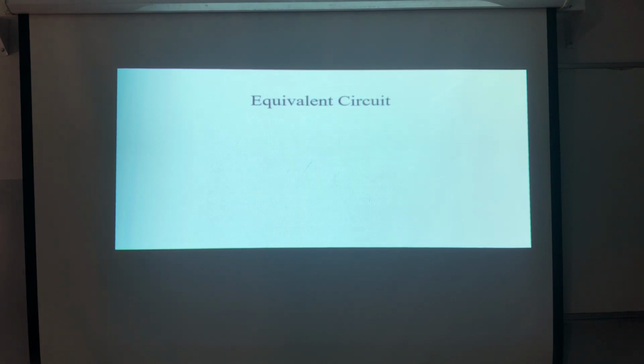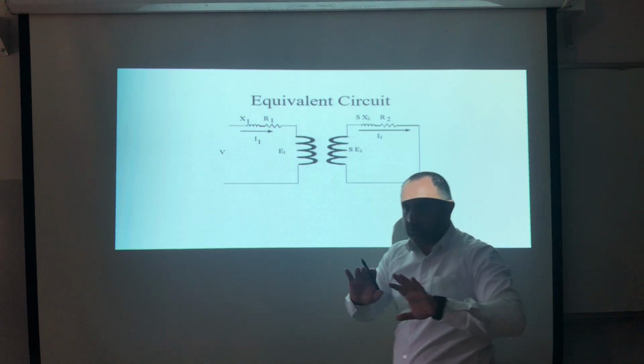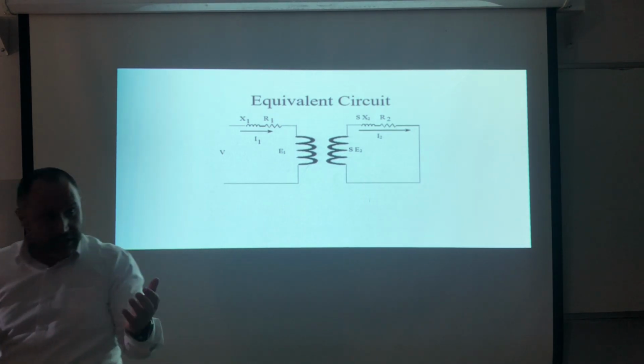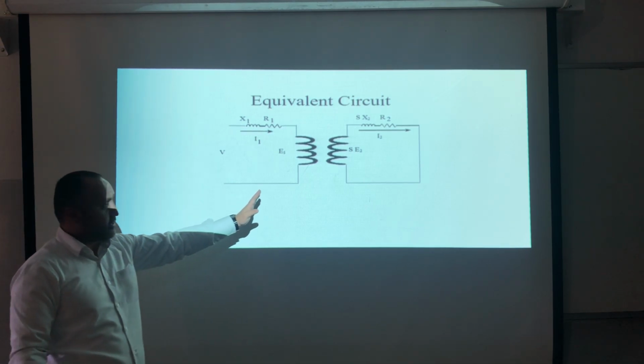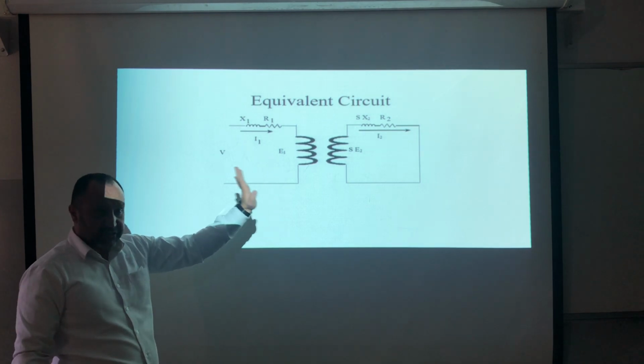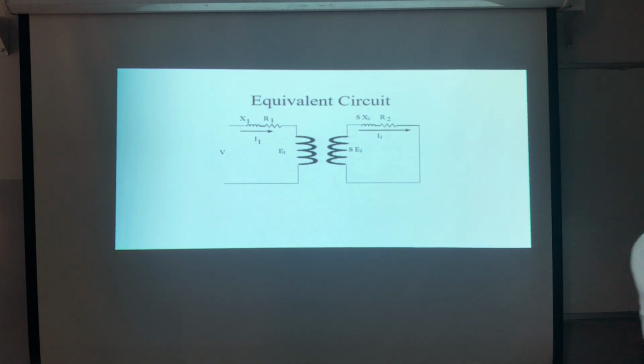Now the equivalent circuit. Now you know that the rotor and the stator, there's no electrical coupling in between, yes? The only coupling in between is what? Magnetic coupling. So simply here, I'm having a circuit for the stator, a rotor, and the air gap. Now, due to the slip, the frequency here is what? The frequency of the rotor is equal to s fs, correct?